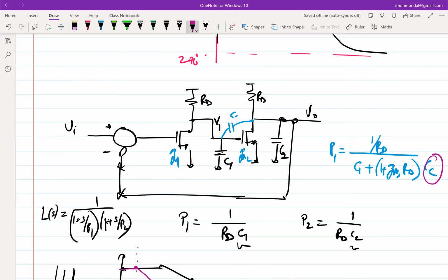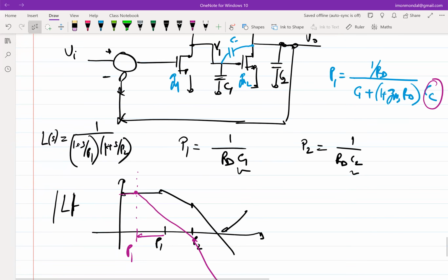And if GM times RT is, let's say, 10, 20 dB, then you can see that the size of the capacitor reduces by a factor of 10. So the 10 times smaller capacitor acts like a 10 times larger capacitor. So that's good. That is definitely good. Now, but an even better thing happens. And you can appreciate that by